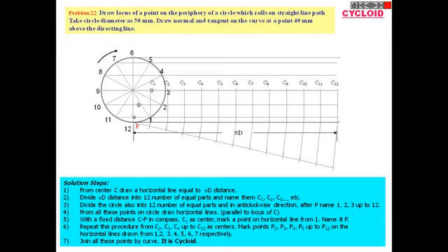Then C3 is the center. Then radius is 25 again. Draw one arc which is passing through the point of 3 to 9. Same for C4, then C5, then C6, C7, C8, C9, C10, C11, C12. Then complete the arc. Notation is important. P1, P2, P3, P4 up to P12, and draw the curve. This is nothing but the cycloid.